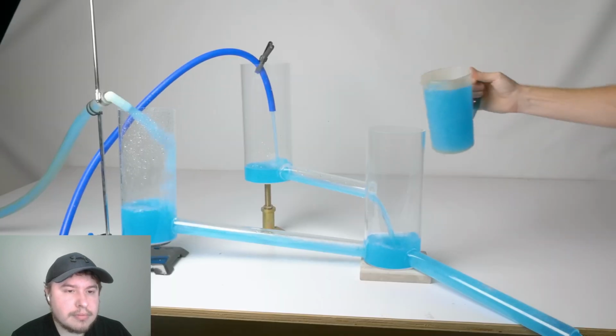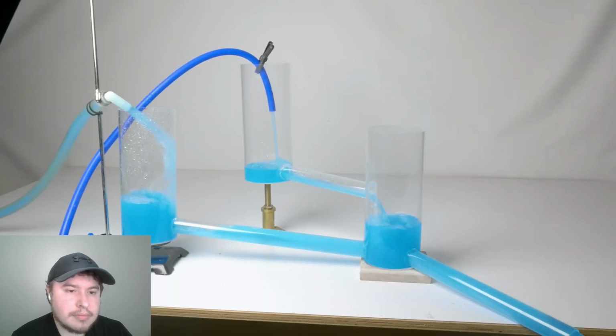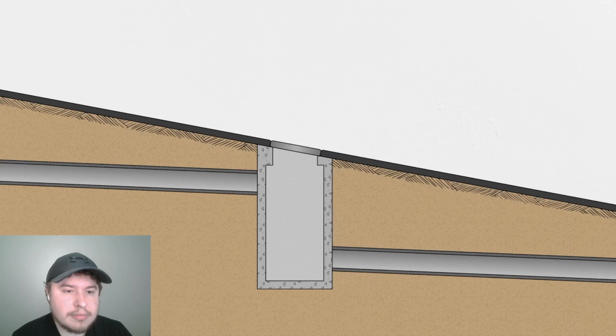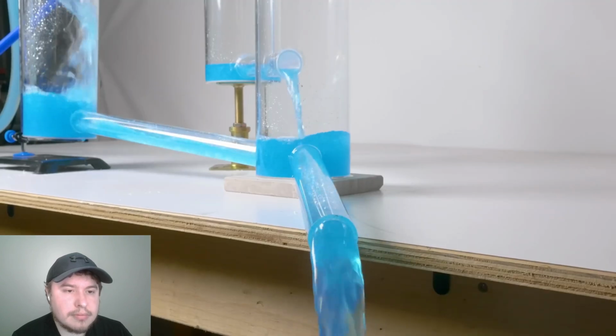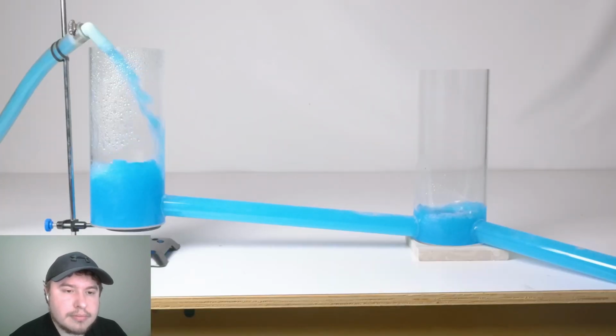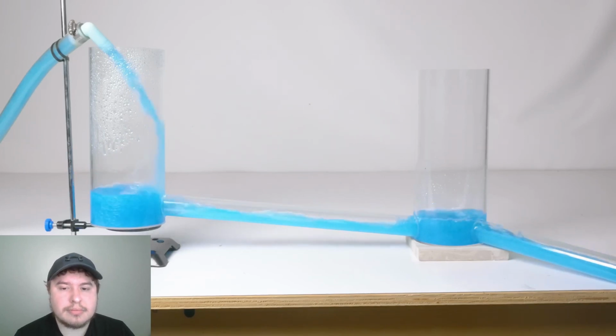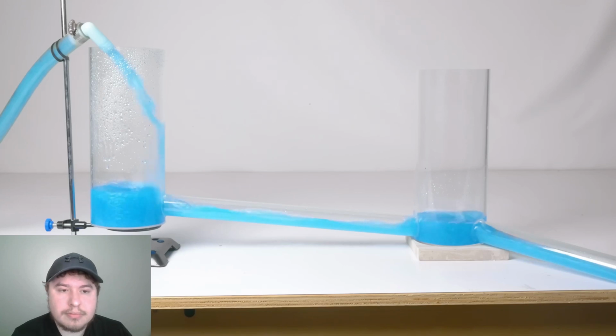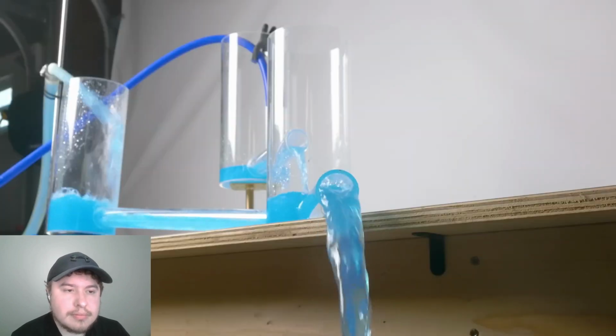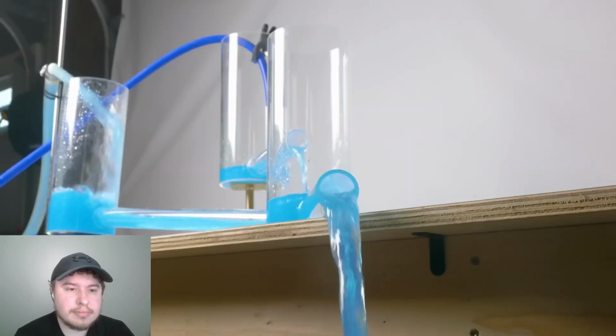It's not normally done this way where my pipe just juts in. You usually don't want a lot of splashing and turbulence in a manhole, again to avoid damage, but also to avoid smells. So most drop manholes use pipes or other structures to gently transition inlet flow down to the bottom. I hope it's clear how useful manholes are by now. Doing it this way, by making the plumbing junctions into access points, just provides a lot of flexibility, while also kind of standardizing the system so anyone involved, whether it's a contractor building one or a crew doing maintenance.